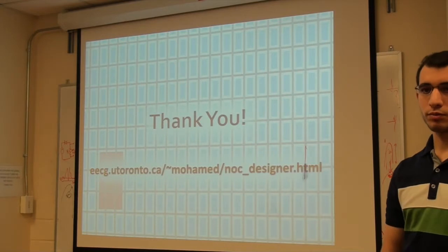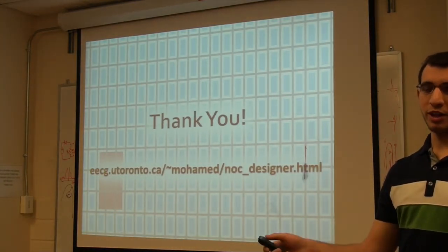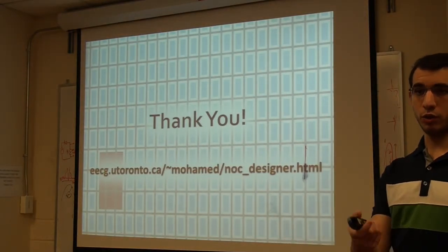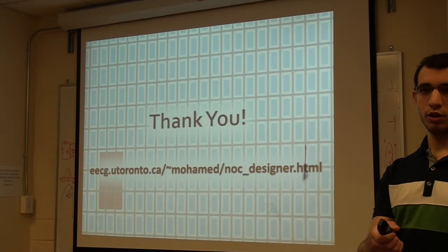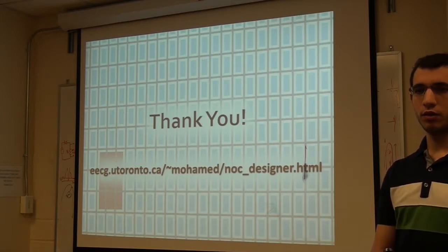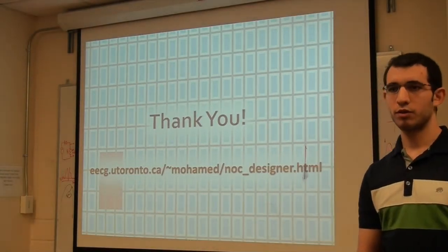Just to follow on to that, which of those did you actually harden for producing your results? So for the last results, it was a hard NOC. Which routing unit do you mean? When you're presenting your area and power results, which of those choices did you end up hardening? So you did dimension order for the hard NOC? Yes. And for the mixed? Same thing.